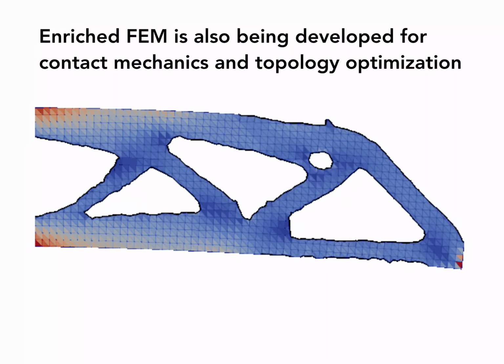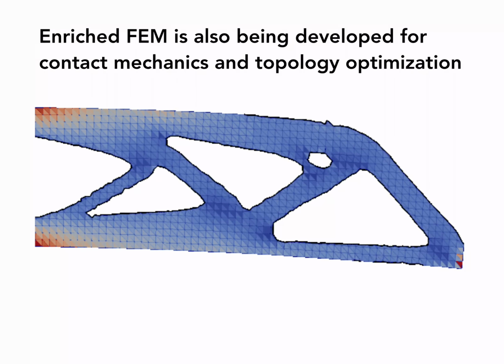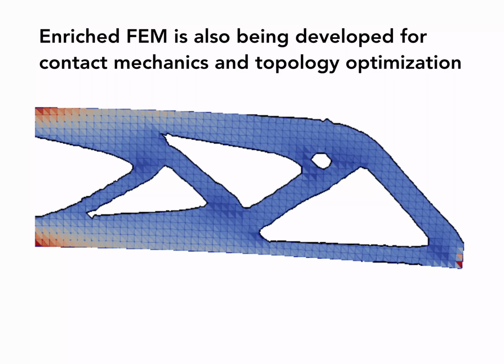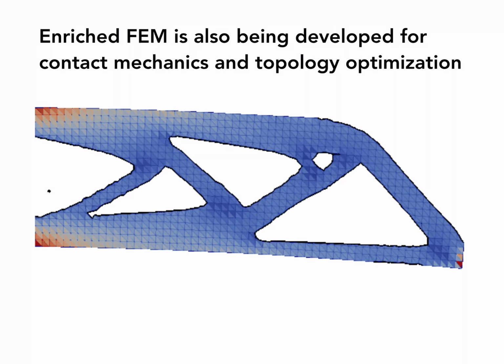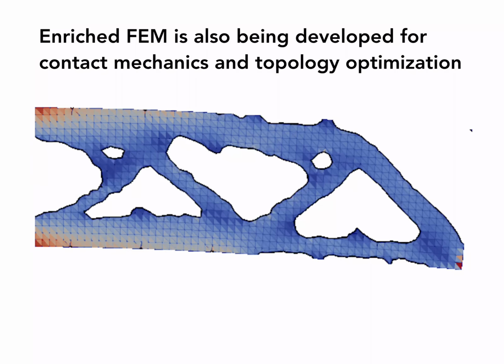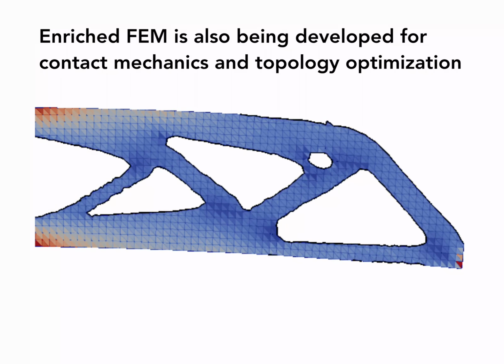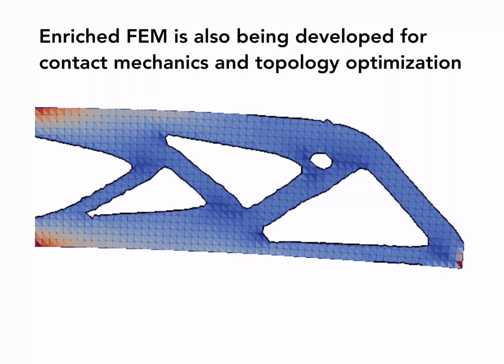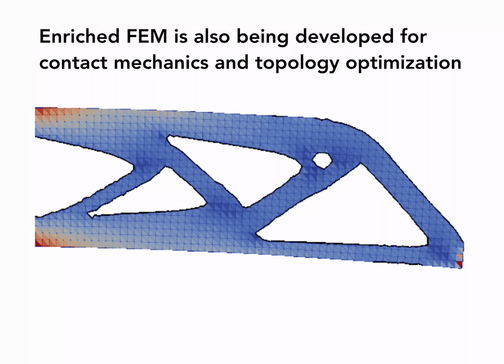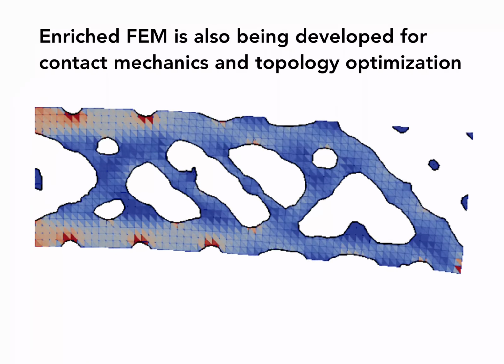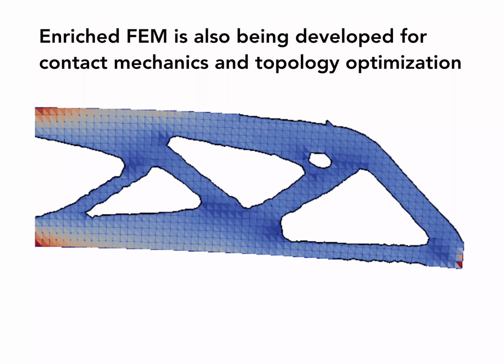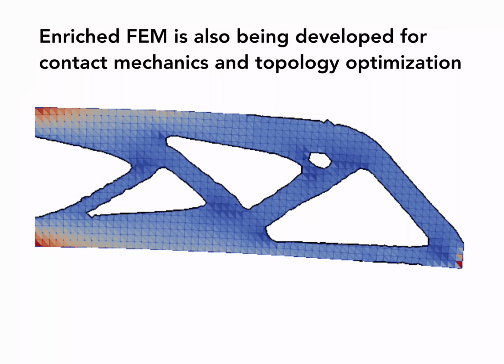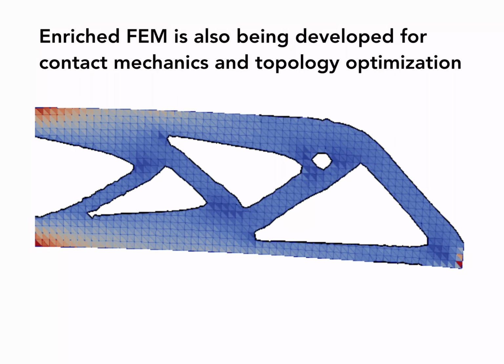Also, topology optimization. This is also my work. So my discontinuity enriched finite element method coupled to an optimizer to do topology optimization. But the cool thing here, who knows about topology optimization? Who took Matthias' class? Raise your hand. Yeah. So the difference between this and the standard topology optimization is that this is not density based, right? So I can cut through elements in any direction. That is super nice.